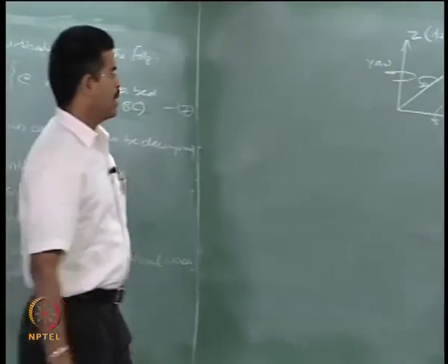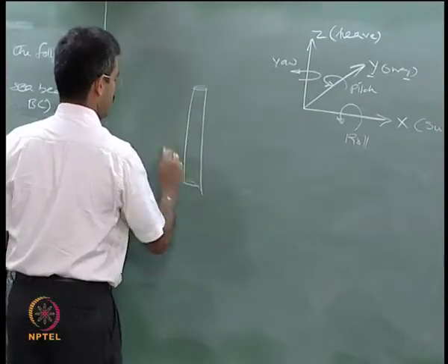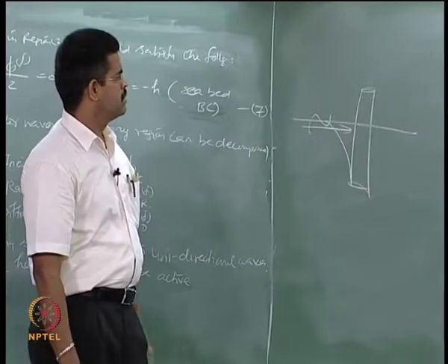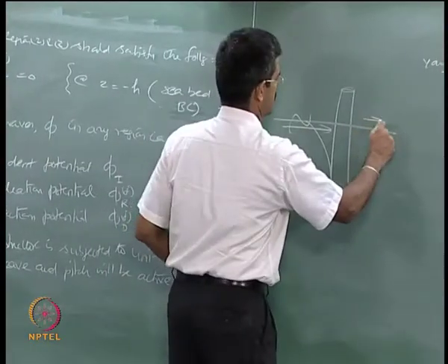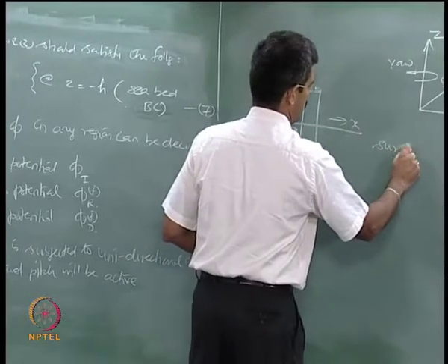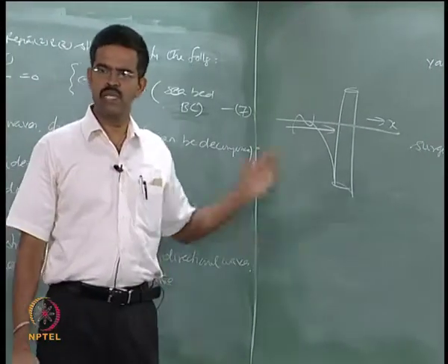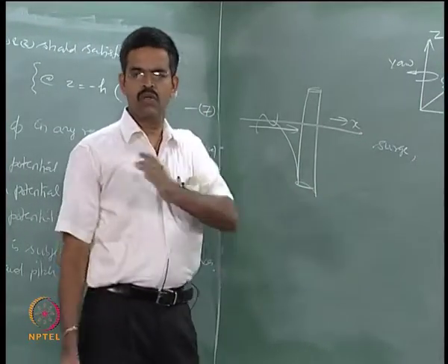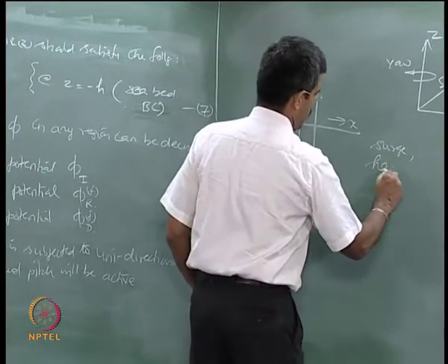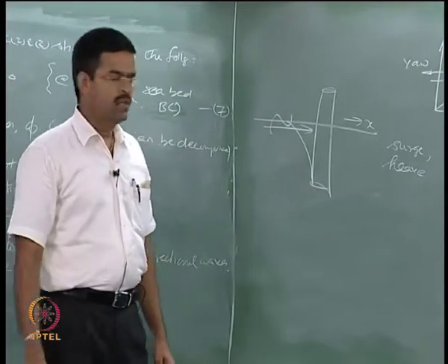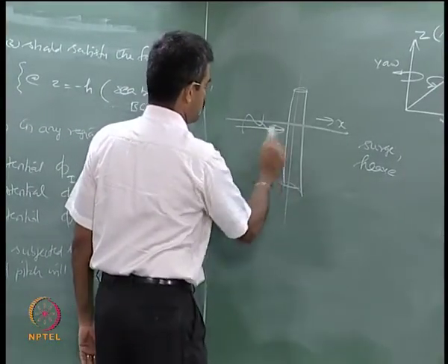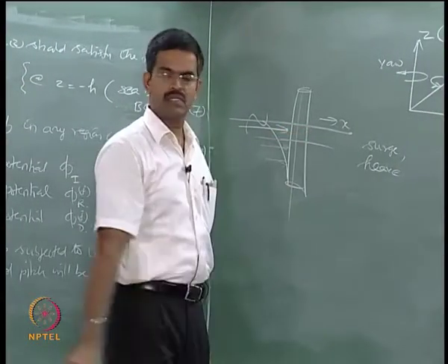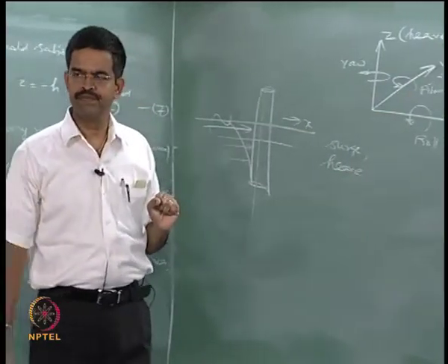yeah. Now I have a cylinder acted upon by some force, velocity variation. So the force, this becomes the x direction, so I will have surge, and we all know in a floating system the set down or the heave and the surge motion are strongly coupled, therefore I will have heave, and the differential forces at any point will cause a moment, and that moment will be about the axis normal to this, nothing but pitch, okay.